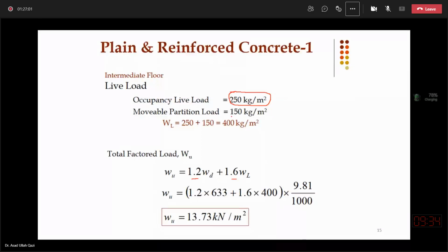add this movable partition. The idea is to first calculate the volume of that partition. You know the thickness of the walls, their lengths from architecture working drawings. You know the height of them as well. So knowing the volume, you can multiply it with density. That will give you total weight of that partitions. Then divide that total weight with the area on which they are resting. It can be converted then into pressure.